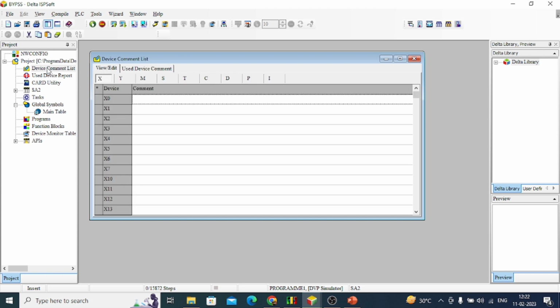Okay friends, now let me create one small PLC program. The objective of the PLC is we need to cut a metal. For that we need one input start stop button and a sensor for sensing whether the cutting part is present or not. For sensing we need another input, and for bypassing we need a third input, and finally the cutting machine, that is the output. We have one start and stop button for starting the machine.